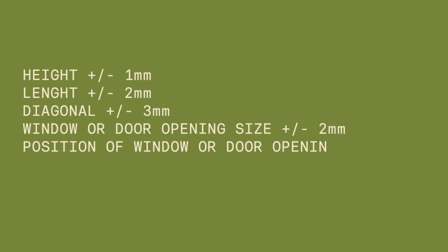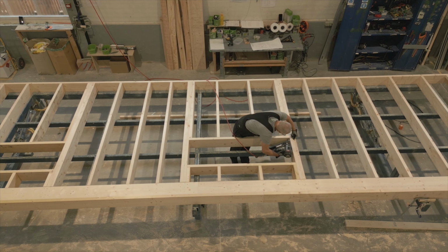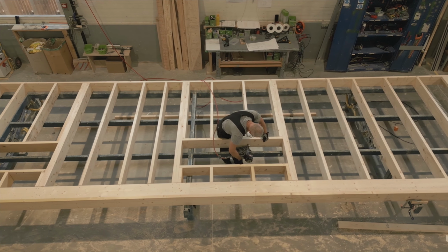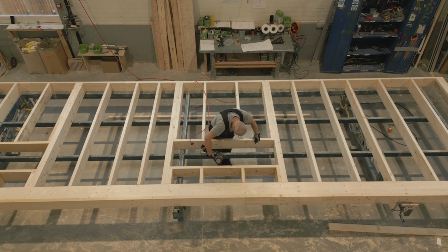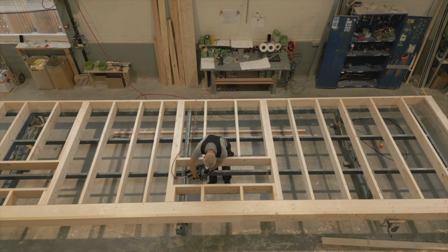Exact manufacturing tolerances are described in the company's system documents or agreed upon separately with the customer. The quality of nailing or screwing must be checked to ensure that nail or screw heads are not protruding.